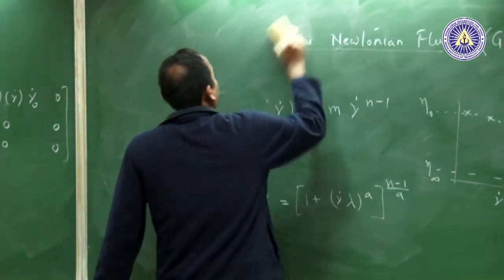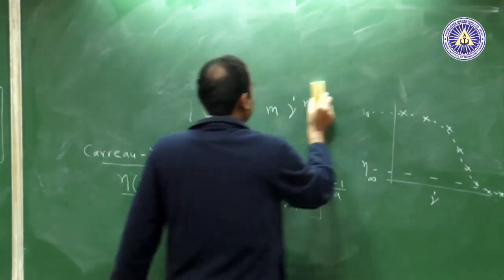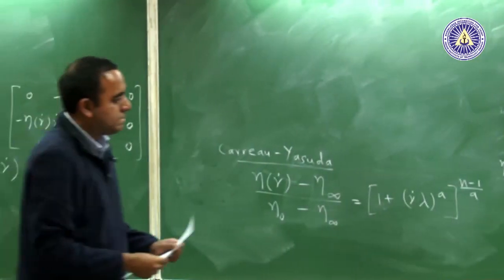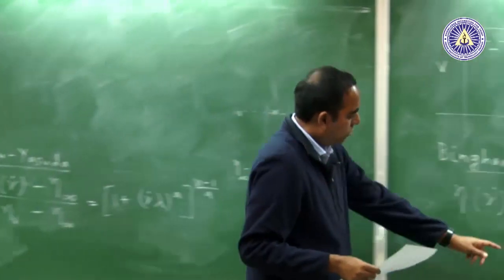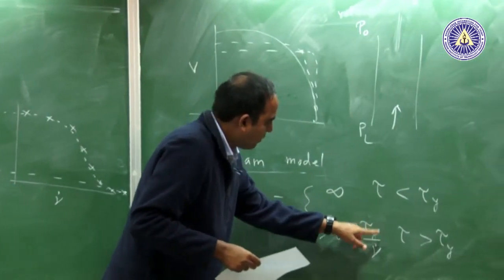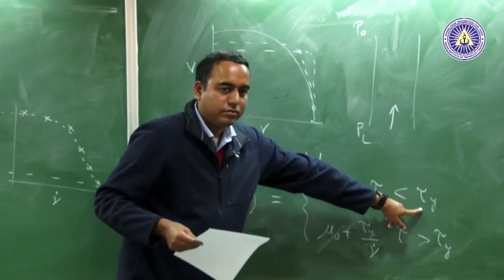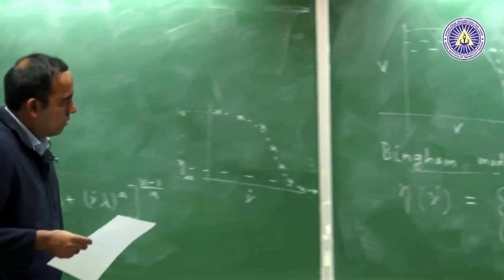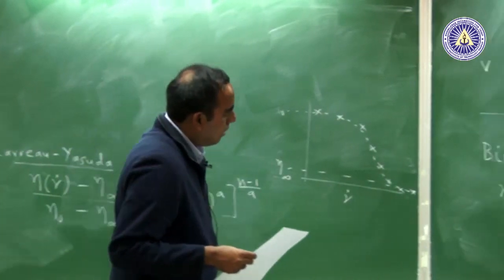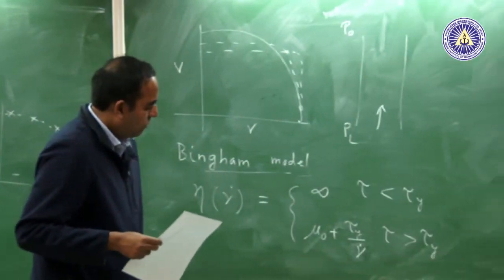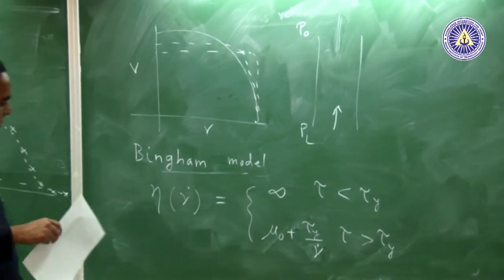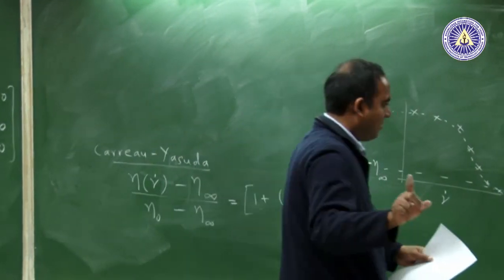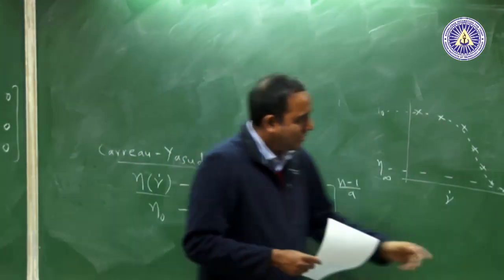this is steady shear, and this is like a power law with which one? This one is like a power law with the yield stress. No. This is a power law. This is tau y, a constant. This is the yield stress. Yeah. So, this is not a... n equals 0. What, n equals 0? Oh, okay. This is just Newtonian.